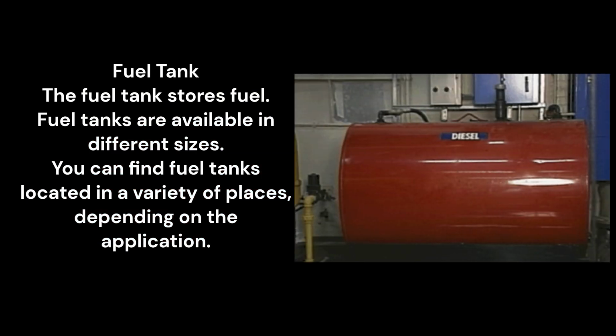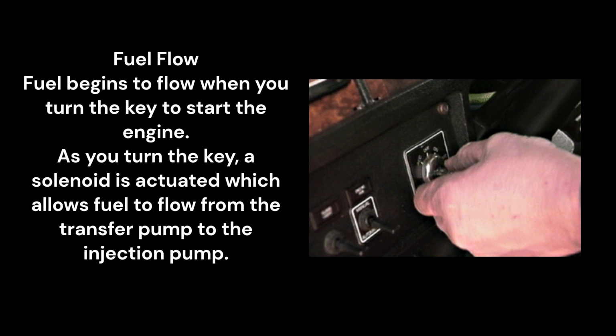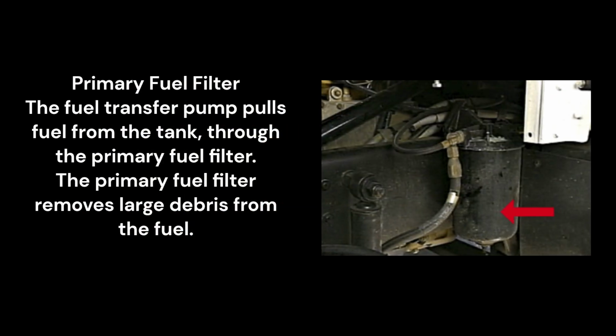Fuel tank. The fuel tank stores fuel. Fuel tanks are available in different sizes. You can find fuel tanks located in a variety of places, depending on the application. Fuel flow. Fuel begins to flow when you turn the key to start the engine. As you turn the key, a solenoid is actuated which allows fuel to flow from the transfer pump to the injection pump.